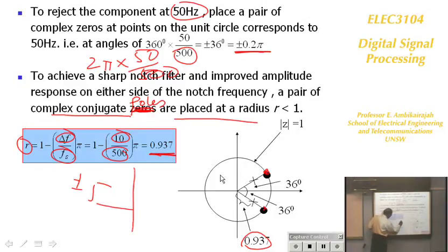If you do that, what are you going to say? You're going to say, right, the poles will produce something like that and down. But it's 0.97, so it won't be very sharp like that. Zero at the same frequency, so it will go down there, dip like that, and then go like that. So this will dip it down, this will pull it out. When eventually this has to be 0 at that point, you can't go further. So the whole effect will be a kind of a step, and then it's a bandwidth, and it just flattens out. That one cancels with that second order.